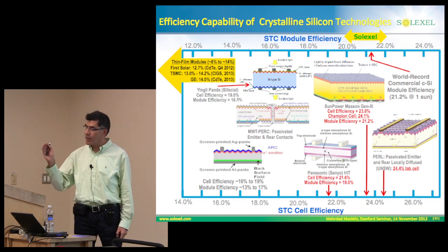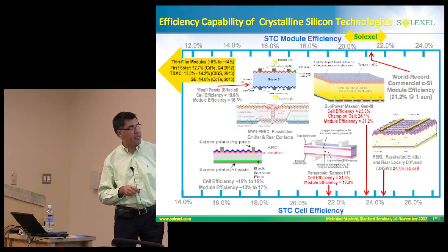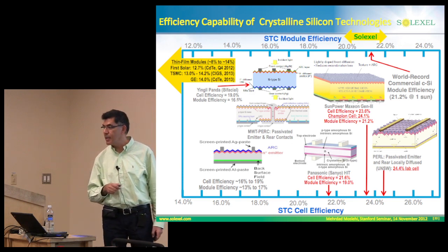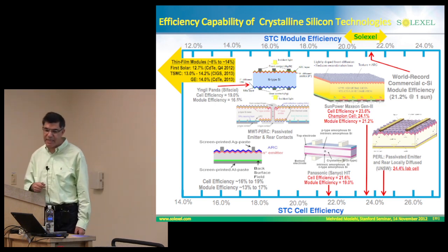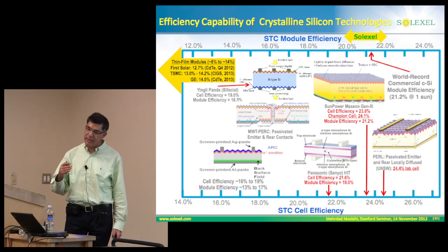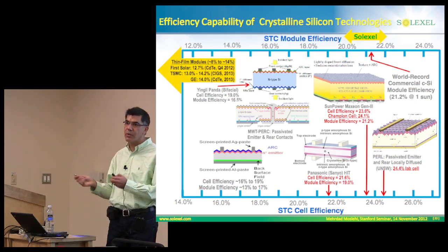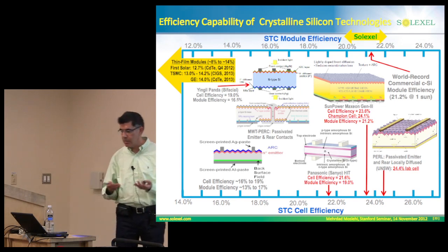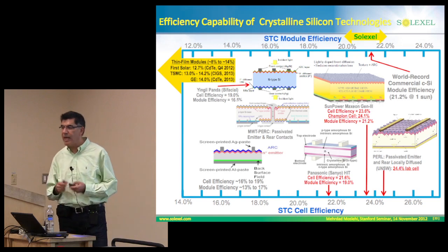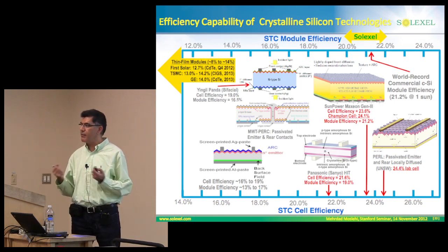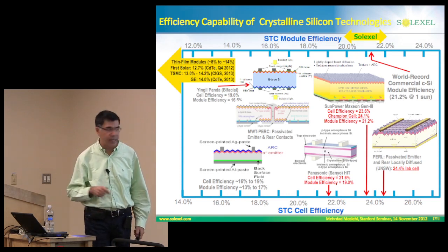There is also significant interest to replace P-type silicon with N-type silicon. And that actually can give you a significant performance advantage. And really, there is general agreement that if you want to get cell efficiency over 20%, you really want to go to N-type silicon, for higher lifetimes. And also, you eliminate the so-called light-induced degradation, because you don't have the mechanism of boron-oxygen pairing defect in the N-type silicon.